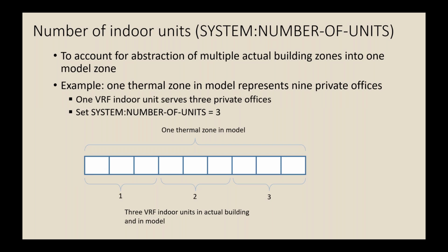If we have a case of, say, a large perimeter, like an open office area, and we anticipate the need for perimeter versus core zoning, in the case that you're doing this model specifically with VRF, is it preferable to proceed with normally zoning it the way you might for a normal system, and have, say, a 10-foot perimeter set of zones for each facade and a core zone, and then specify 1 VRF as far as number of units per zone?